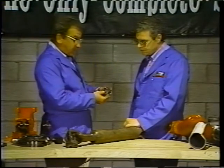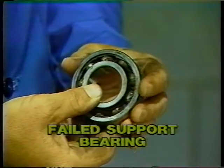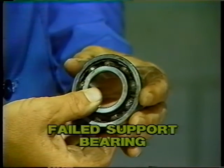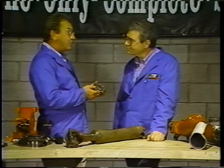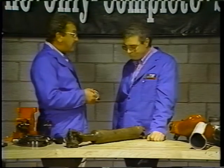The last component that we have here is a failed shaft support bearing. Now, these sealed bearings help support multiple section drive shafts. And because they're sealed, they never need lubrication. Now, if they don't fail simply because of old age, they fail because of torsional vibrations in the driveline that should have been investigated. That about wraps it up.